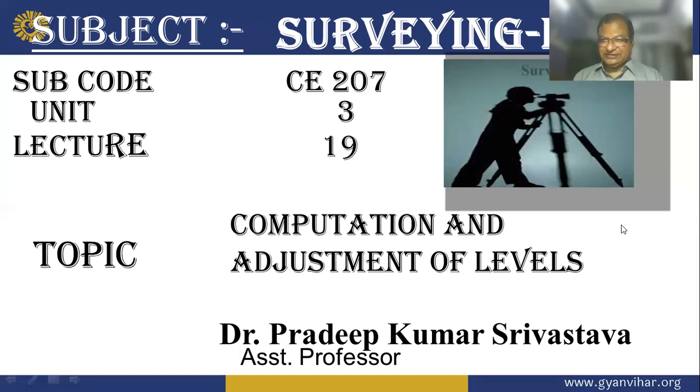In the case where you are doing double leveling survey and the staff man has not opened the staff fully, both will be wrong, and there is no way to adjust the error.